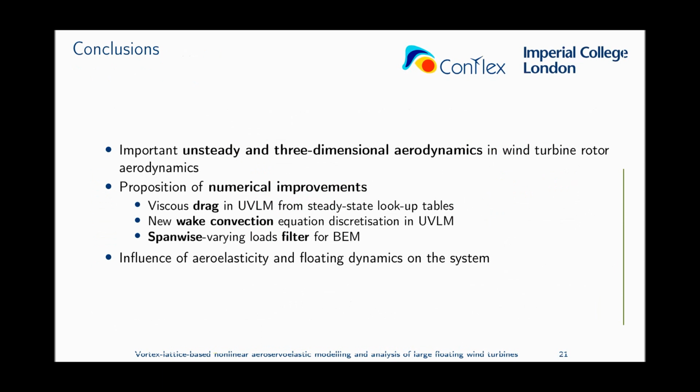So I would like to conclude by saying again that unsteady and three-dimensional aerodynamics are very important for rotor aerodynamics. We have proposed some improvements for low and medium fidelity methods, such that we have increased their accuracy without significantly increasing the computational cost. We have reduced the computational cost of UVLM by the new wave convection equation discretization. We have included drag in UVLM following the BEM philosophy. And we have included three-dimensional effects in BEM based on a study performed with UVLM. And we are finishing now how the elasticity and the floating dynamics influence the behavior of our system.